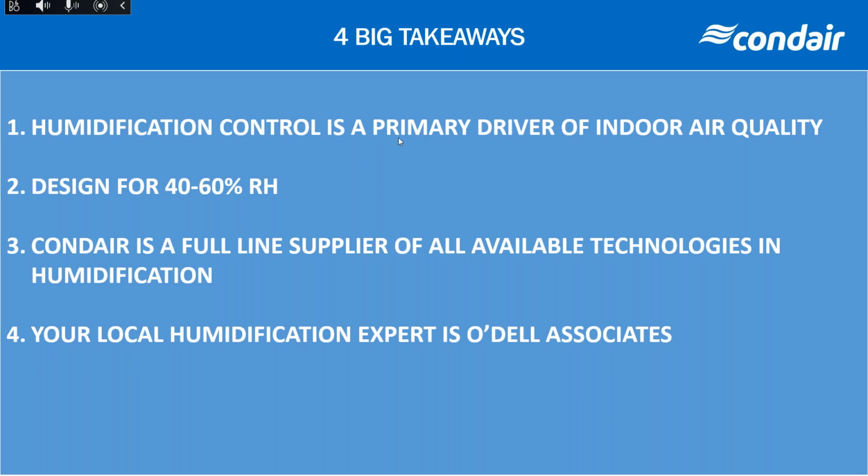Did you have any comments? Yeah, I would suggest static is one thing, and obviously health is another. Generally, if there are people in the space, 40% would be the minimum number I'd want to see, and that is effective at managing static charge. If you could get us the chart, Jerry, I'd very much like that, and I can get that off to the person who asked. Definitely. And it's not only static in the wintertime, as we've all touched our computer or our desk or our lamp, but also the dryness in the skin and the eyes, all the things that Dr. Taylor talks about. So it's still 40% at the end of the day.